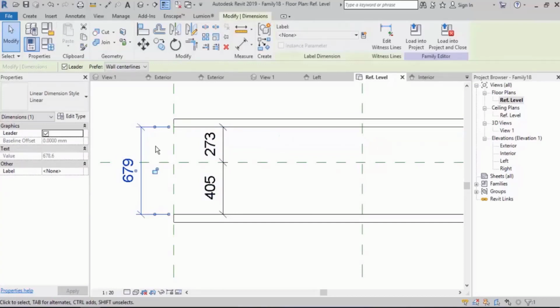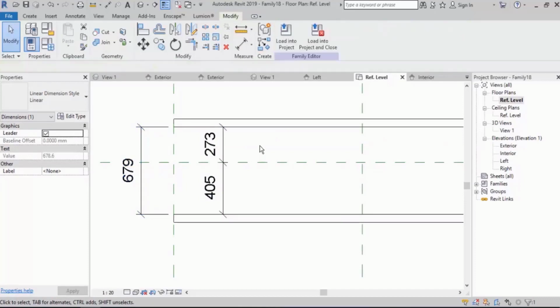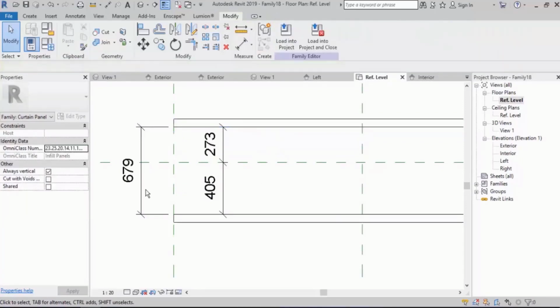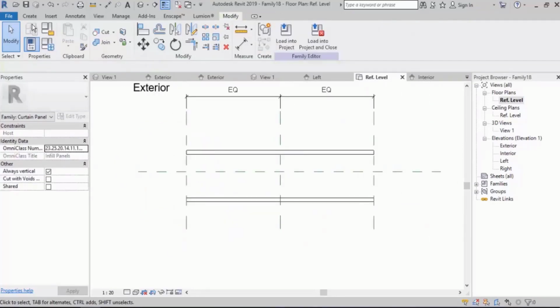Don't connect a dimension to it directly. This is the advice you might get from many pros. When you want to make the distance from an object to another object or another reference plane parametric, never connect a dimension to it directly. So draw another, extra reference plane.